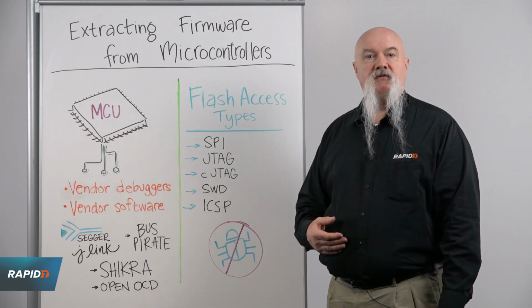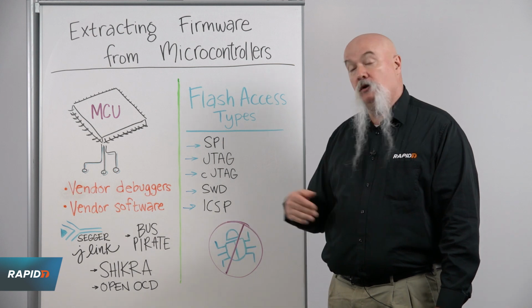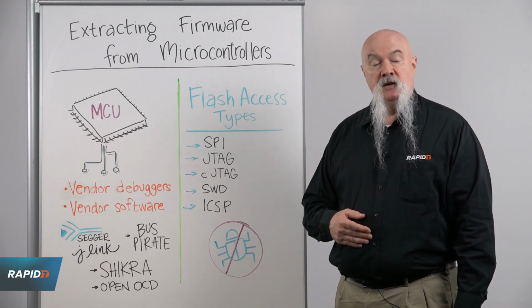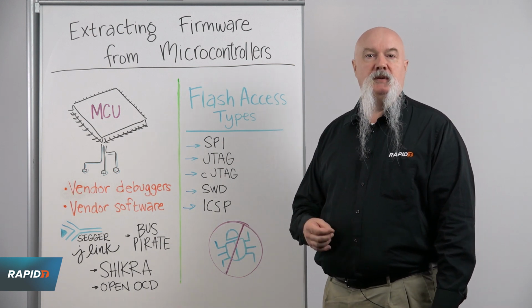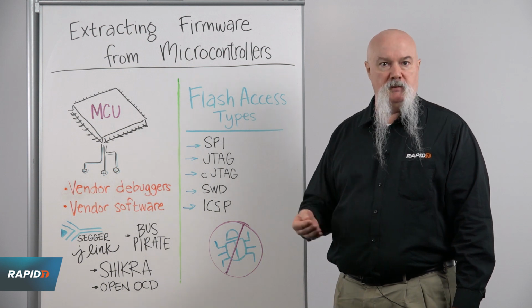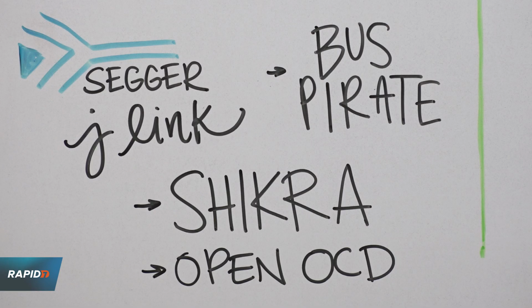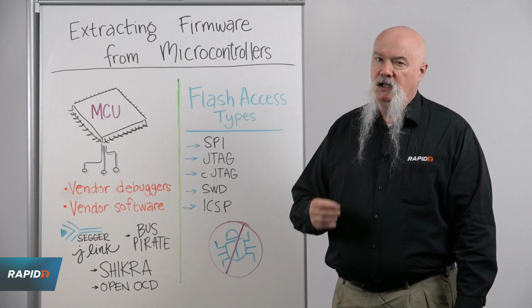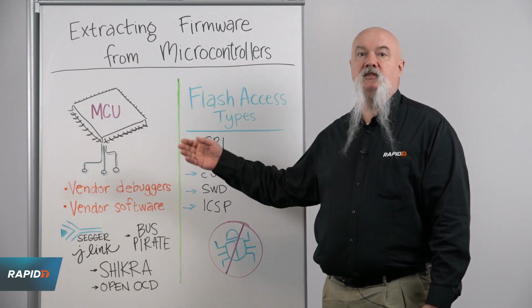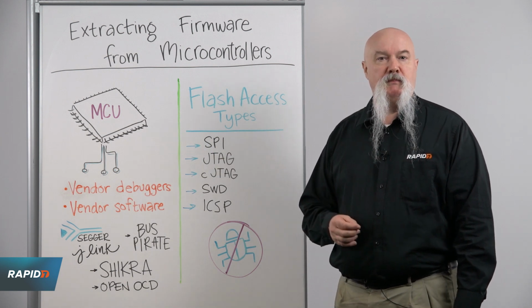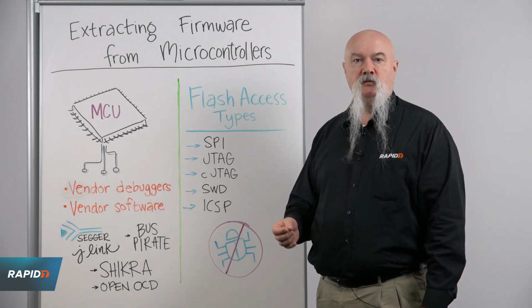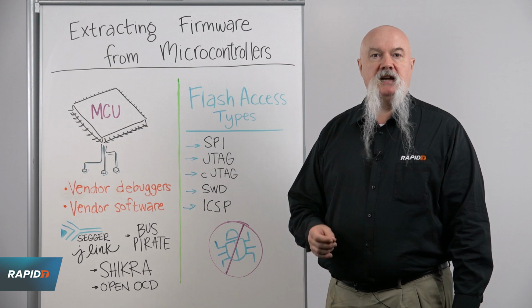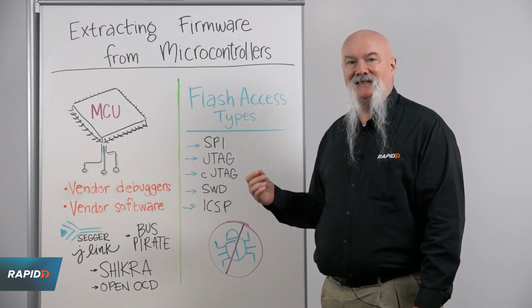And to work with those devices, you have access to software known as OpenOCD. The OpenOCD software gives you the ability to work with a number of different chipsets. But again, often OpenOCD may not cover specific chipsets. In those cases, I step back to the vendor-specific debuggers and vendor-specific software. Often that is the most effective and quickest way to actually access these chips.